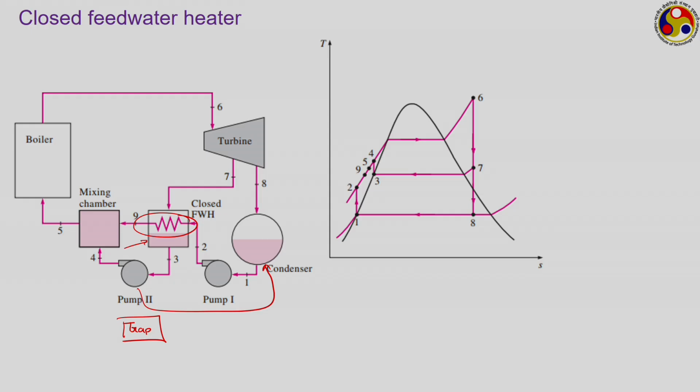Look at the subsequent TS diagram. Here again, if 1 kg of mass is getting expanded in the turbine, y fraction of that has been extracted at state 7, and the remaining 1 minus y fraction completes the turbine expansion and then passes to the condenser, then it passes to the condensate extraction pump also. So, this state 1 to 2 is also corresponding to 1 minus y fraction.